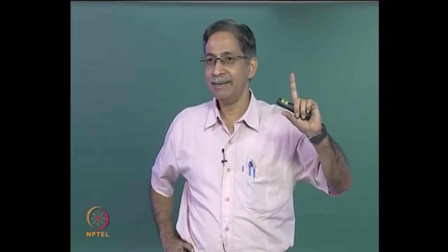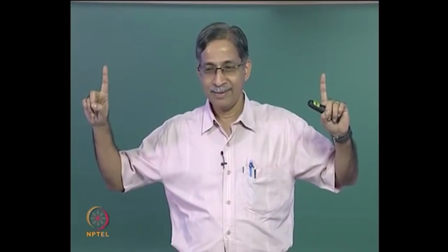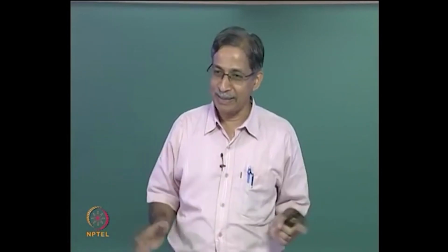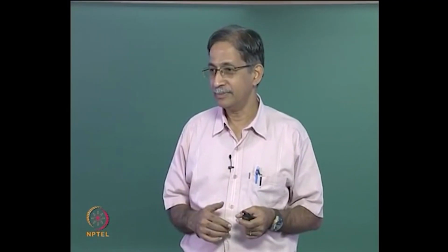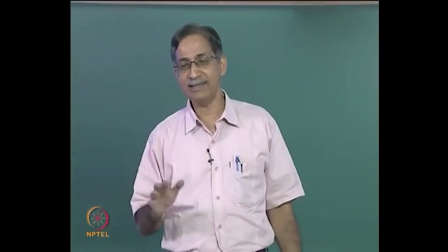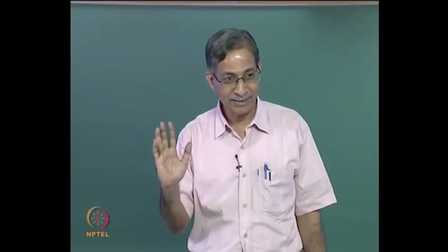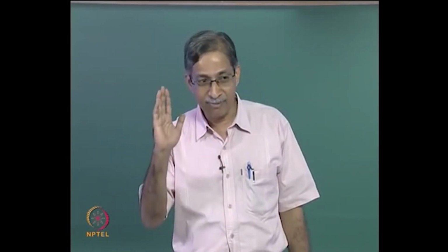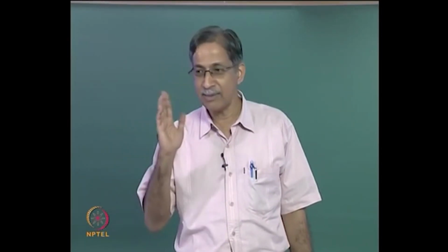Let's be very clear. This is a statically determinate beam. Your midspan moment will not always be WL by 4, whatever you do, plus P delta is what you do in second order analysis. That's what you should say. In first order analysis, the answer will not change. Even if you had material non-linearity, it will not change. WL by 4 remains WL by 4, even if the beam yields. It remains WL by 4.